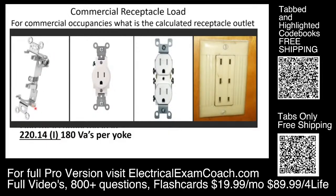What this code is stating is that whether we have a single, a duplex, or even this old school triplex here, each one of those would count as 180 VAs each. I like to think about it as each gang counting as 180 VAs. So if I have a single gang box, it's 180 VAs. If I have a 2-gang box and they're both containing receptacles on each side, it would count as 180 VAs per gang, and so on and so forth as you went to 3 and 4 gangs. Anytime you're dealing with a device strap, whether it has 1, 2, or 3 receptacles on it, it's 180 VAs per yoke.